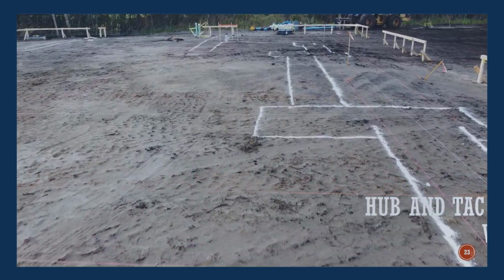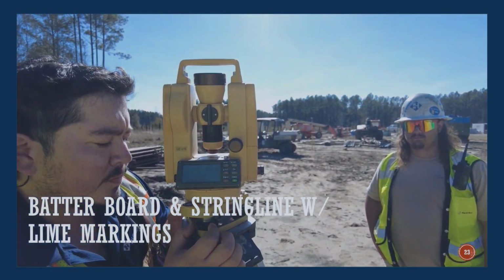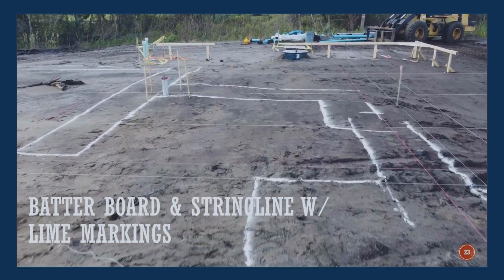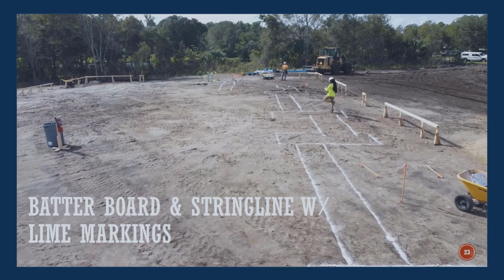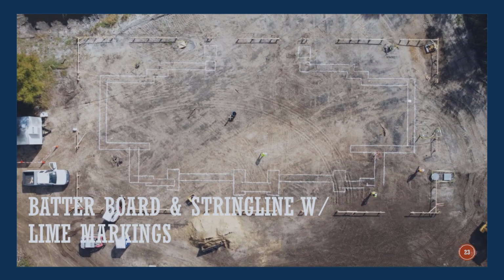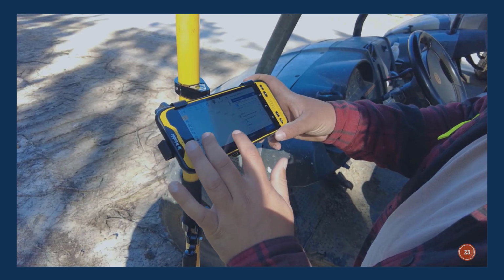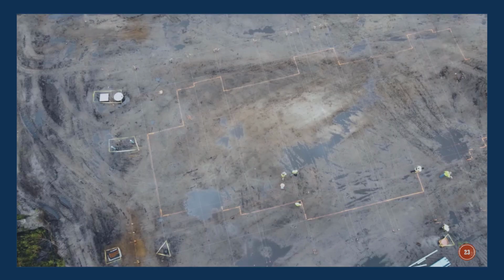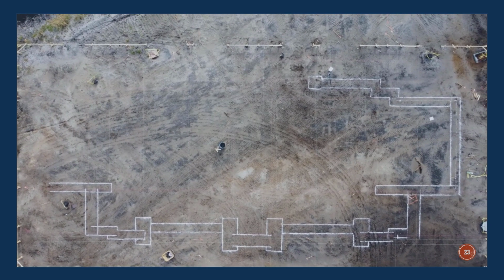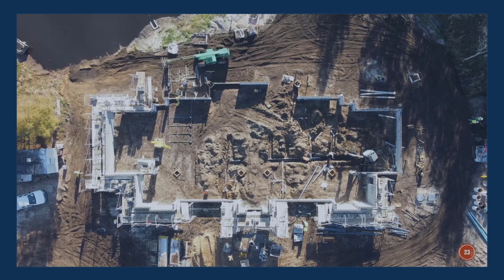Second, we set up batter boards and string lines with a theodolite, also called the transit, and laser level. With batter boards, we use less established points by the surveyor and create building points of our own, like measuring off of a single established column line and making our own building controls to measure from. Or we can use technology like a Trimble to set established building points directly on the ground to build and measure off of. You are always going to have to understand the use of offsets, column lines, and exterior wall face lines to build the structure square and efficiently, and most importantly, right the first time.